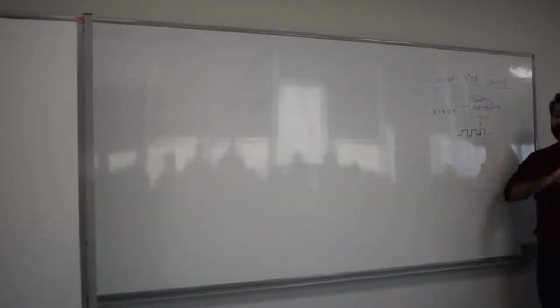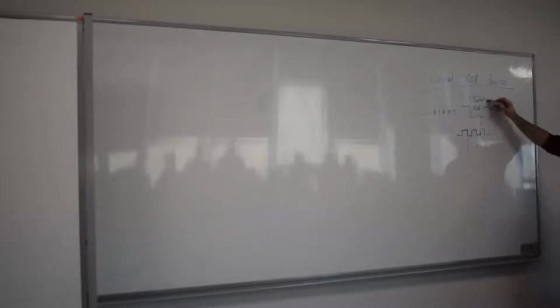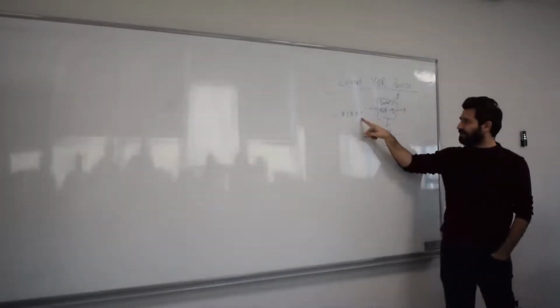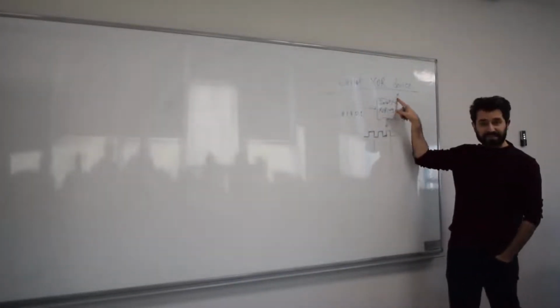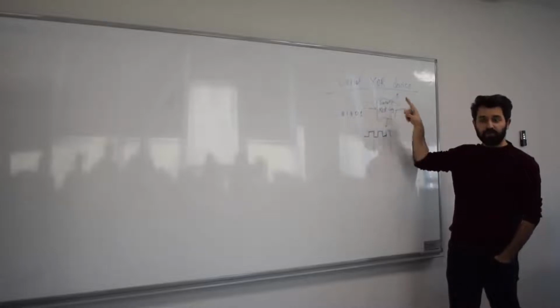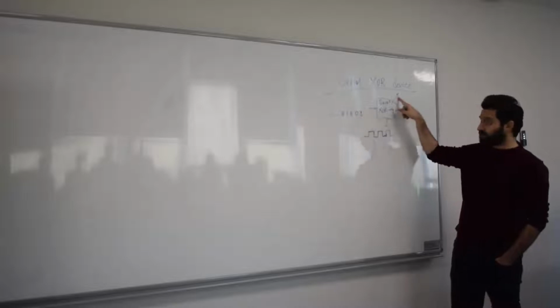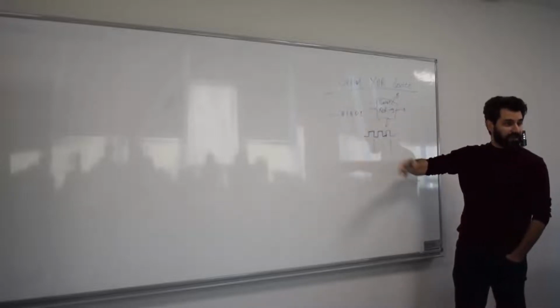Let's suppose that the serial XORing device starts at state 0, and the first bit comes in the first clock cycle. That bit is XORed with that state value, 0, and that would create your new state, which is 1 now, right? Because 1 XOR 0 gives you 1. So that's your next state.